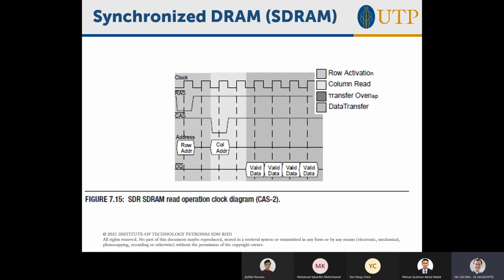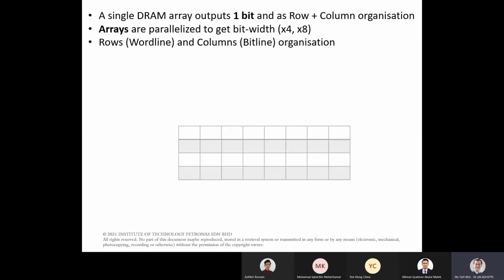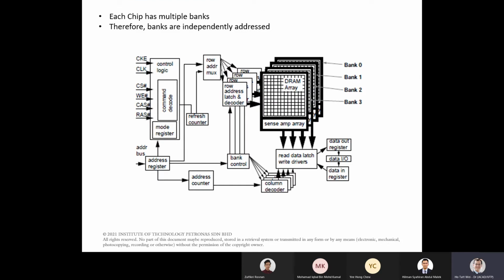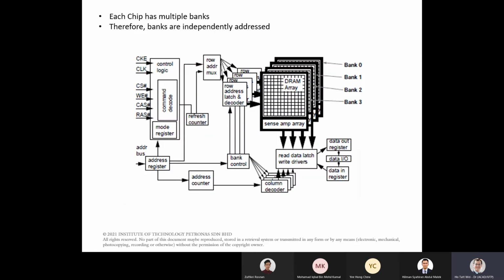Yes. Okay. So I want to pipeline this, and I'm telling you that the read process, the pre-charge, the sense, the amplify, and the restore, the access and amplify, is a very long process, right? So the way I do that is, instead of one bank, I'm going to have 4 of them. One bank can output 8 bits, for example.